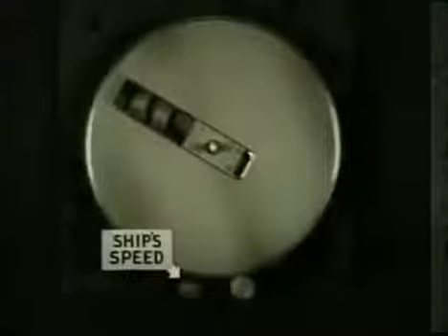The pin extends up through the slot in the vector gear so that pin and follower can move only along the slot. Ship's speed is entered through this input gear. With a transparent vector gear, you can see how the spiral groove moves the follower and pin along the slot.